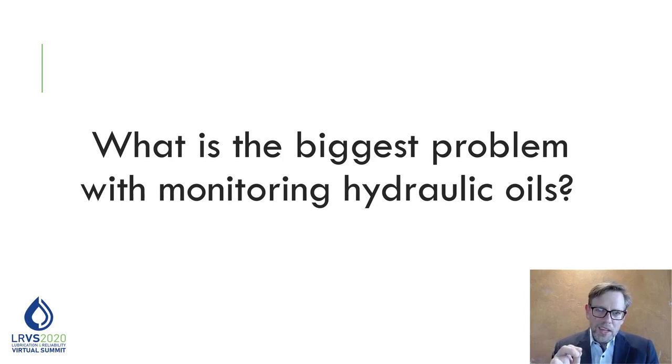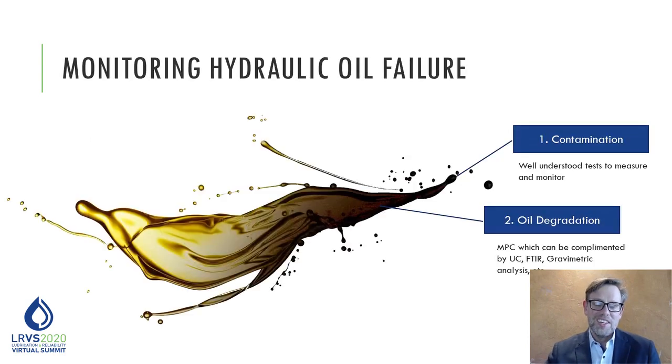However, now we're coming to the most important point that I want to make. The number one issue that we see in hydraulic oils is, in fact, that we have these fluids failing due to degradation. However, we're not actually running the right tests. So on the oil degradation side, luckily we actually have tests available that are very, very useful, and we've applied them in various other verticals.